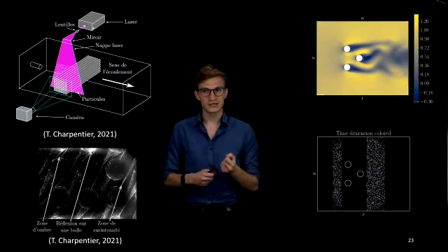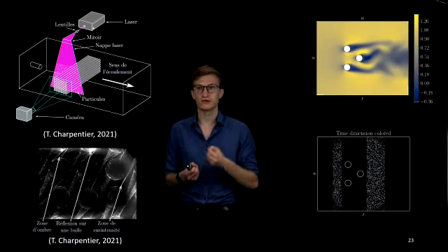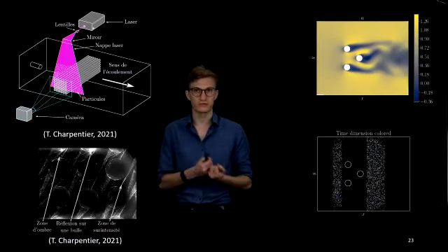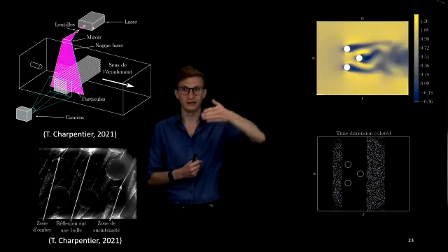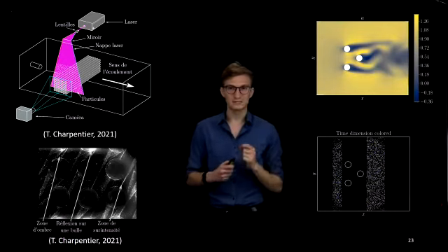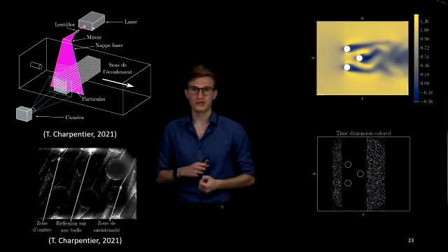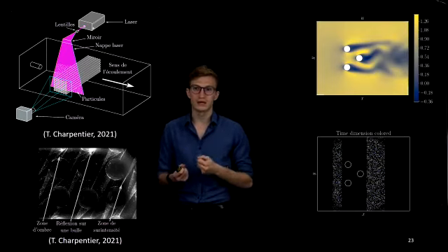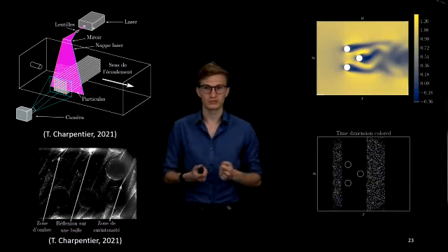And the problem is that in that application, you want to make the refractive index of the water and of the cylinders match together so that you minimize the reflections of the laser in the cylinders, etc. But even by adjusting as best you can, you still have some reflection like this, which causes uncertainties, imperfections, and also requires post-processing.